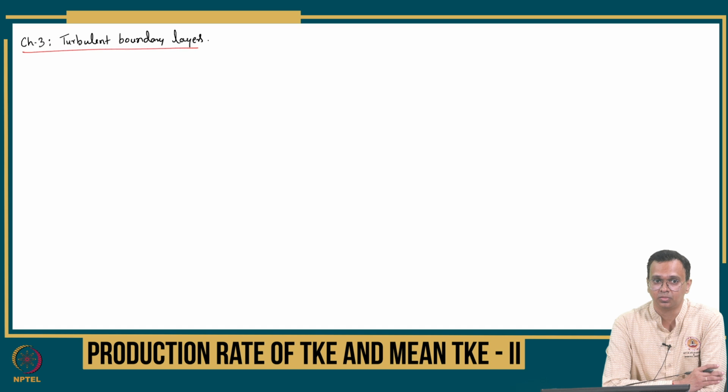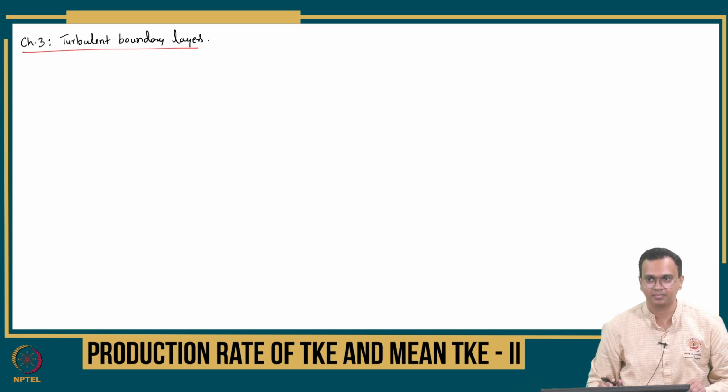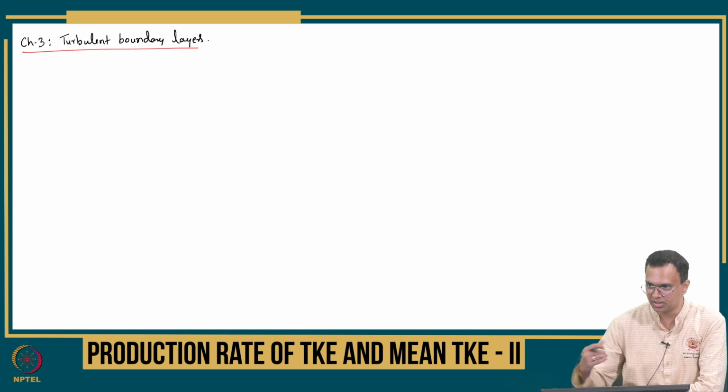What does wall do? In the context of turbulence, wall does many things. So when you think of a turbulent flow, what comes to your mind? Vorticity, right? Vorticity, all eddies going around. So what does wall do to this vorticity? Walls generate vorticity, right? Without walls, how do you generate vorticity? It provides that shear, it provides that rolling motion of the fluid, right?